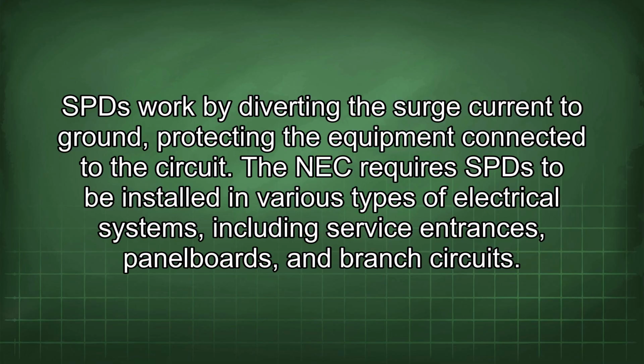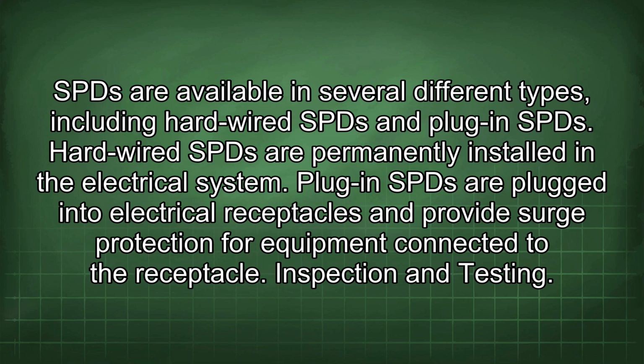The NEC requires SPDs to be installed in various types of electrical systems, including service entrances, panel boards, and branch circuits. SPDs are available in several different types, including hardwired SPDs and plug-in SPDs. Hardwired SPDs are permanently installed in the electrical system. Plug-in SPDs are plugged into electrical receptacles and provide surge protection for equipment connected to the receptacle.